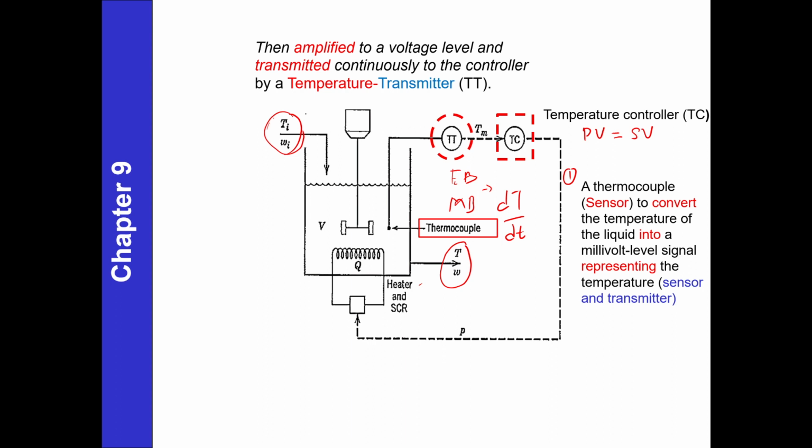That's why last time you saw the plus and minus block in Simulink. We set the value here, and this is the current value, and the difference, which is SP minus PV, is the error, and that is also how much corrective action should be taken by the controller, since this is a feedback loop.